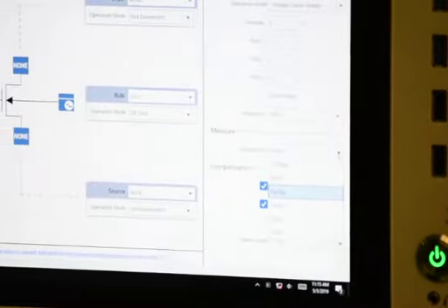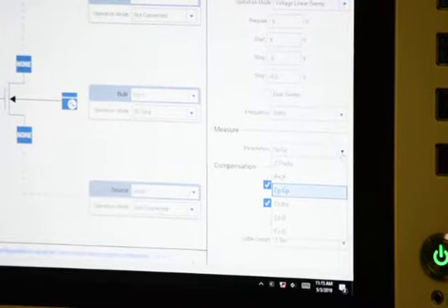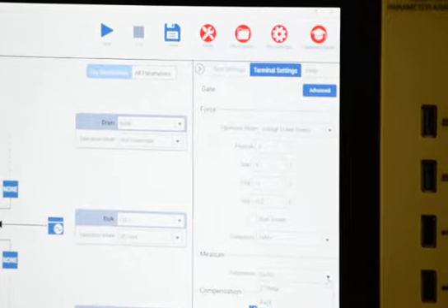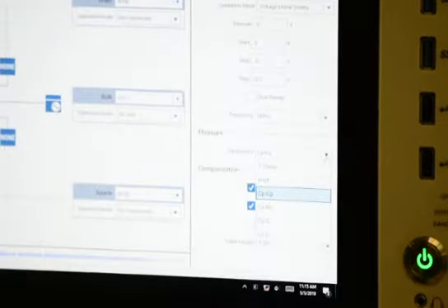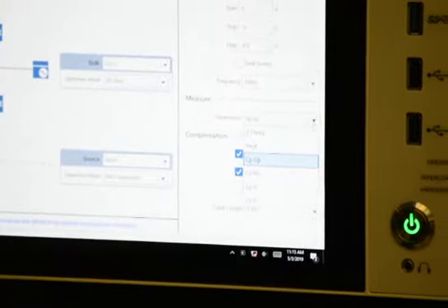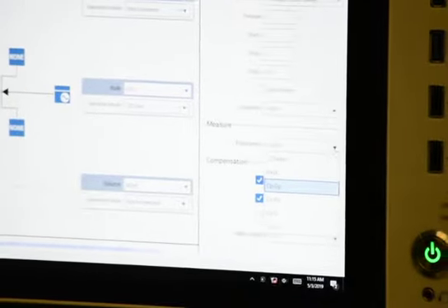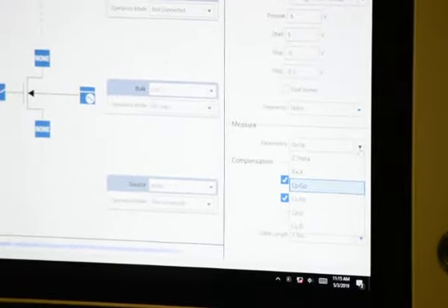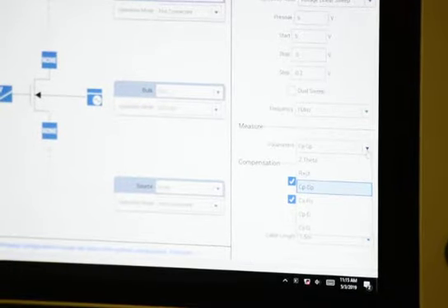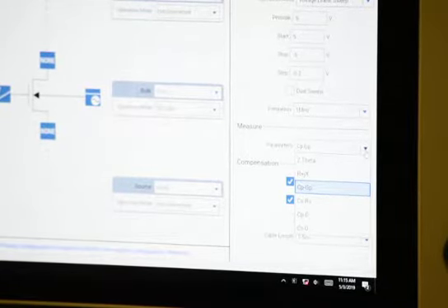Because we might have a leaking capacitor. Because your error can go up real fast as dissipation factor goes up. It'll still give you a measurement, but it's going to be off due to the leak. There's a way you can calculate how much error based on dissipation factor as well, and it's in our manual. But you can get 50% error real quick with elevated dissipation factors.